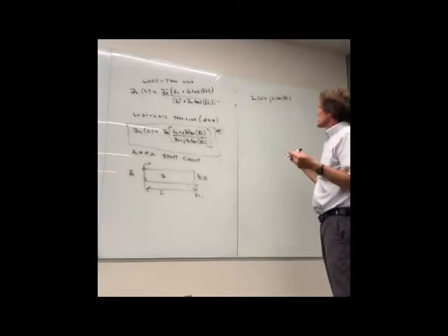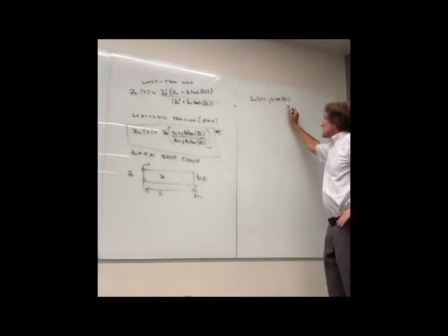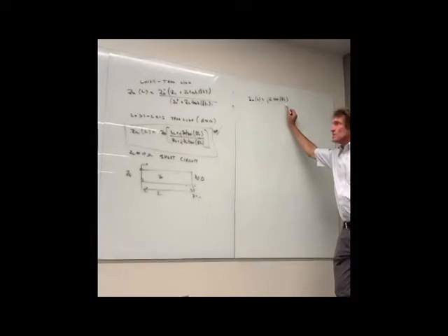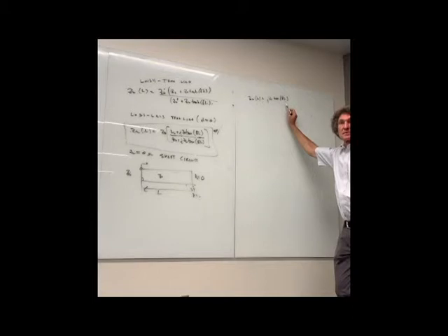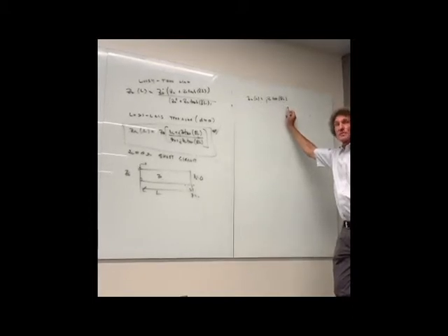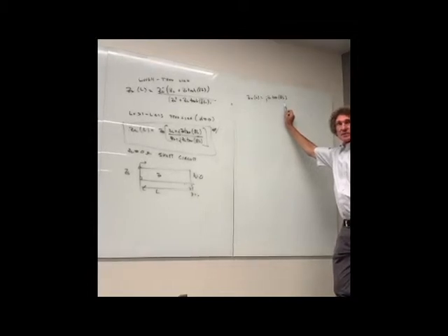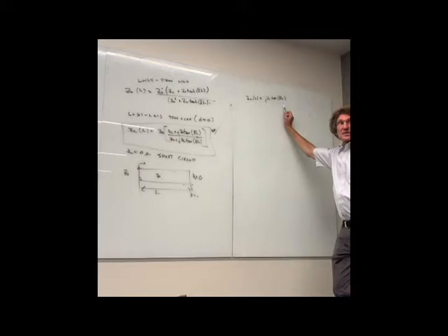Now think about the extremes in value. Beta L represents an angle, right? What happens if I'm at beta L equals 0? Remember, we have a short circuit. What is the value of the input impedance? What's the tangent of 0? It's 0. So you would expect 0 ohms, and in fact, you get 0 ohms, right? But what happens when beta L is equal to pi over 2? What's the tangent of pi over 2, or 90 degrees? It's infinite. It's approaching infinity, isn't it?